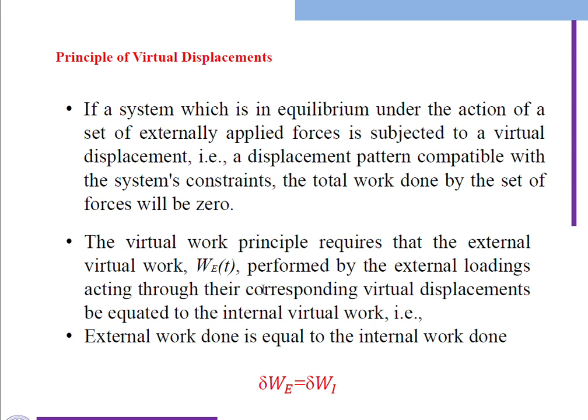If you see, the external work done means all the loads into the displacement of each individual load; we get one work done of the body. For each load we calculate the total work done of the external load. And similarly, the body which resists this total load and displacement, that one we call the internal work done.